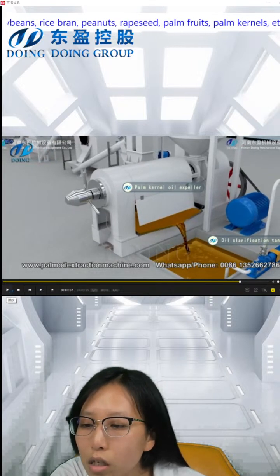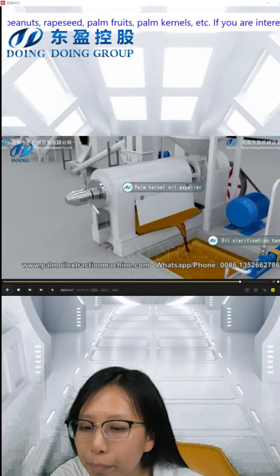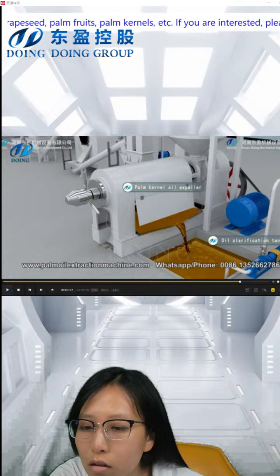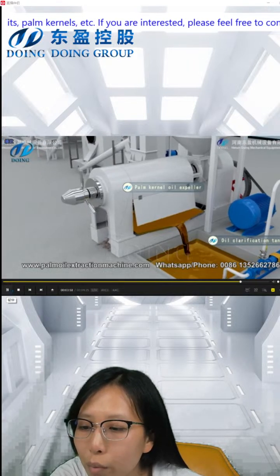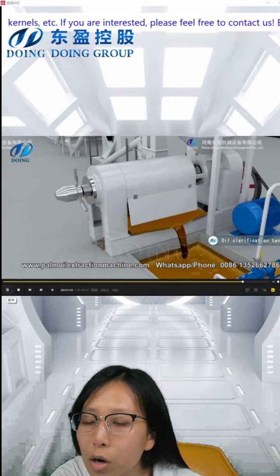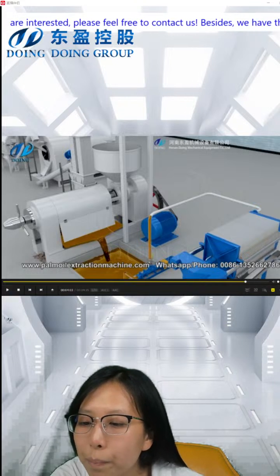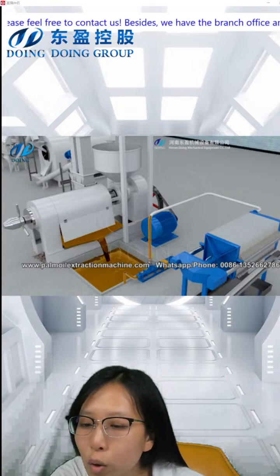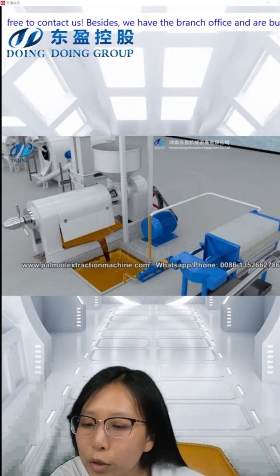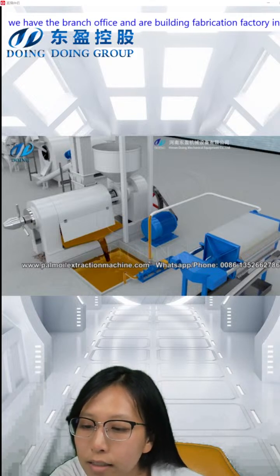This is our palm kernel oil presser, which is a kind of screw oil presser. It is also called a round roll oil presser, more wear resistant, easy to operate, and more convenient when replacing parts. Our screw press adopts the short steam pressing process. If the material stays too long in the chamber, it will lead to paste blockage and a poor pressing effect. Short steam pressing can avoid this situation.